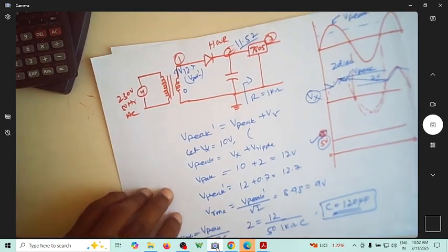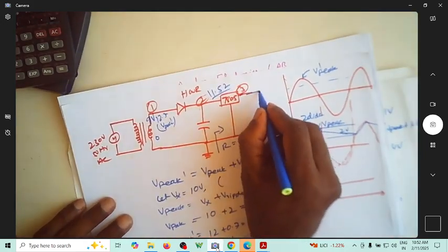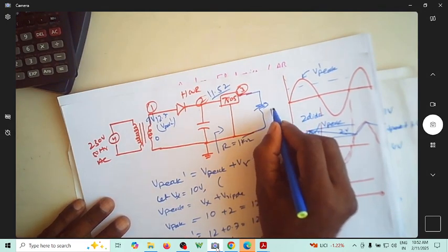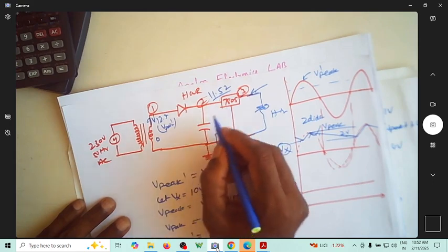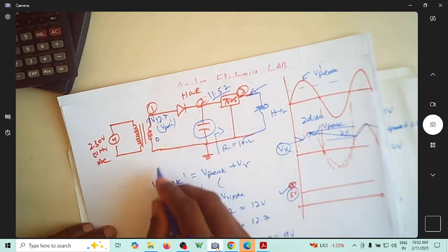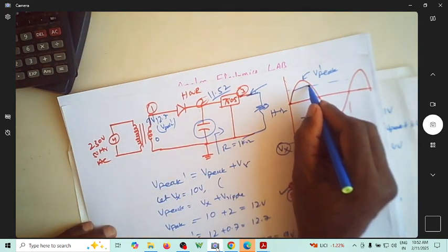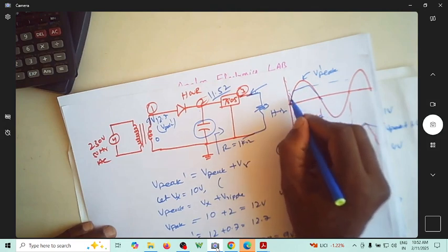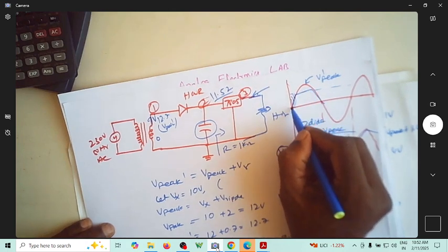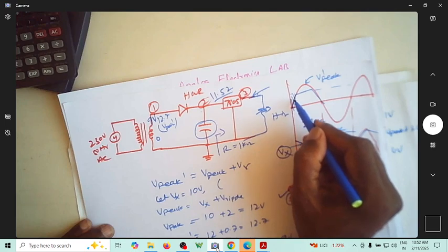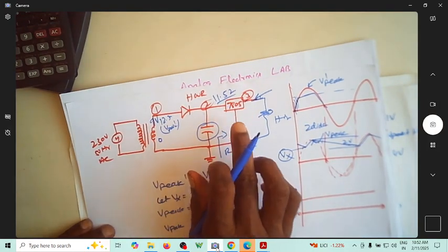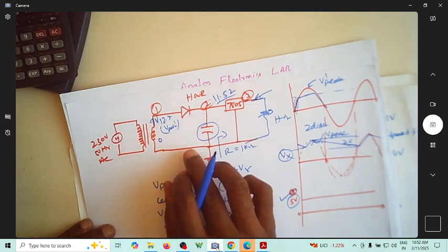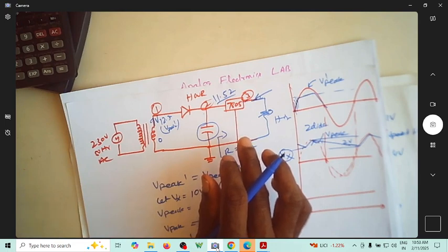To do the load and line regulation, you can start putting some DRB, start with a very high resistance, start reducing the resistance, and observe the output voltage. To see the line regulation, take out this capacitor and you'll get a waveform something like this. Try to put the cursors at different points and see that if the input voltage is less than the minimum required, the output will not be stable. The output will become constant only if it is more than 7.5 for 7805, more than 14.5 for 12 volts, and more than 17.5 volt to get a constant 15 volts.